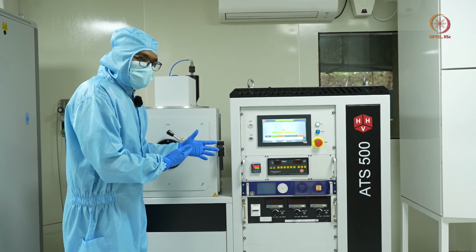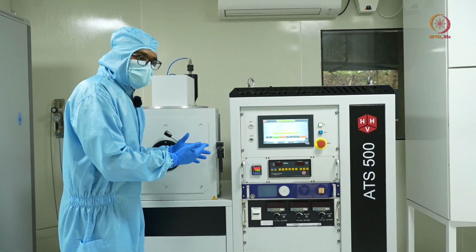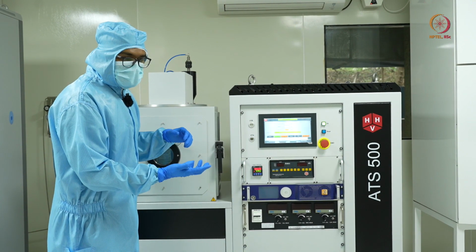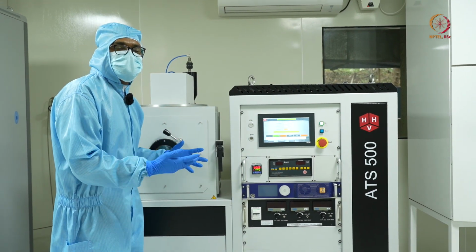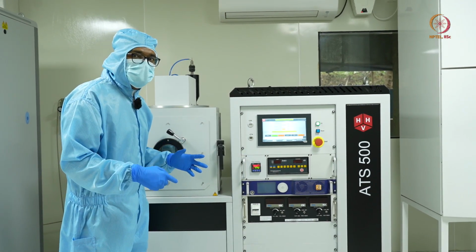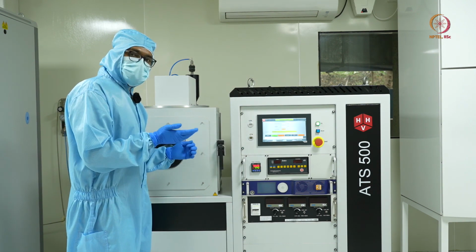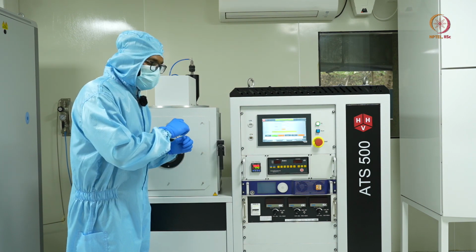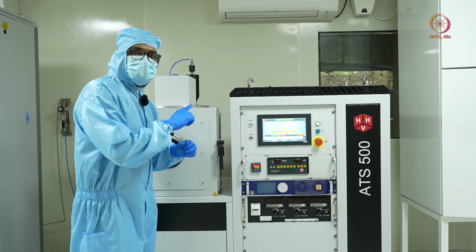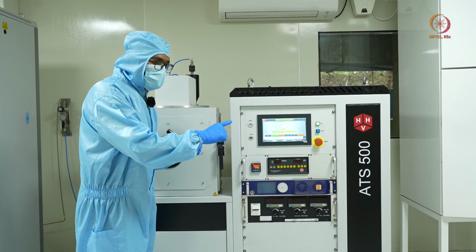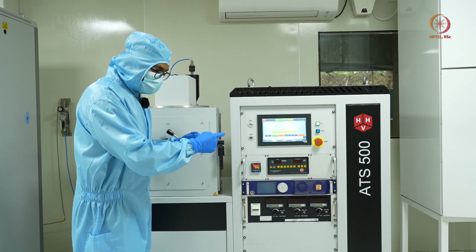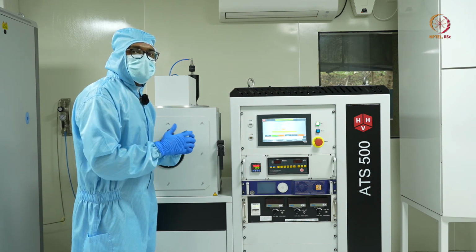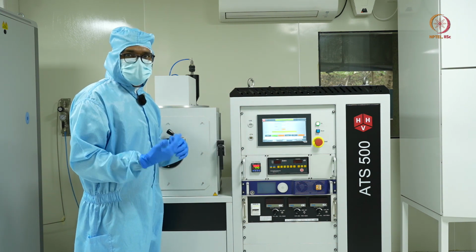What will happen initially is the roughing pump will come into action and reduce the pressure from the atmospheric pressure, that is 10 to the power plus 3 millibars, to a high vacuum of 10 to the power minus 3 millibars. Next, once that is done, the next action would be of the turbomolecular pump, working in series with the rotary or the roughing pump, to reach a very high vacuum of the order of 10 to the power minus 6 millibars.